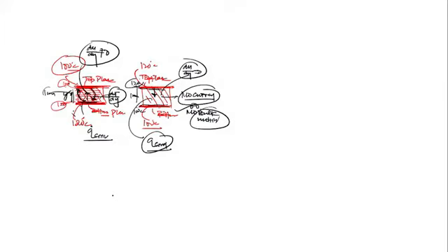So whenever there is a velocity gradient, how is it possible? It's very common sense to say, for example, let's say this is a flat plate. Try to understand physically why the velocity gradient will increase the temperature gradient. Now listen. Let's say one case when the fluid is stationary. Then obviously the first layer and second layer, I'm talking about two layers. This layer of fluid is at 100 degrees Celsius. This layer of fluid is at, let's say, 80 degrees Celsius. And let's say this thickness is 1 millimeter.